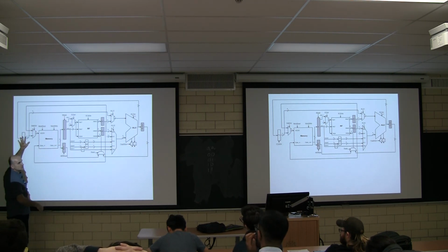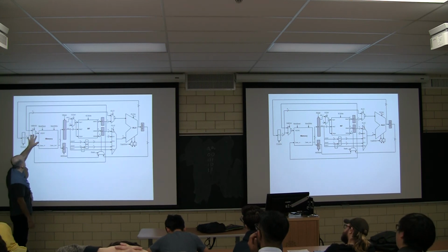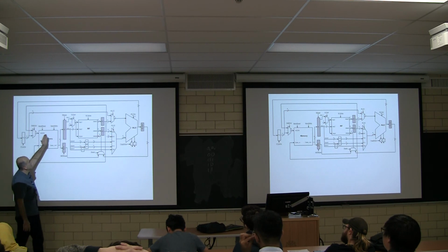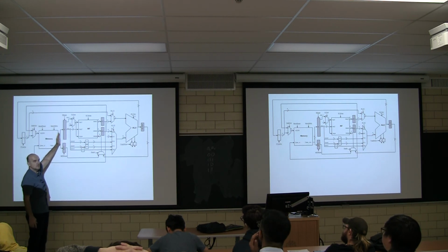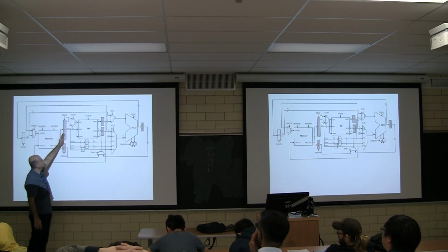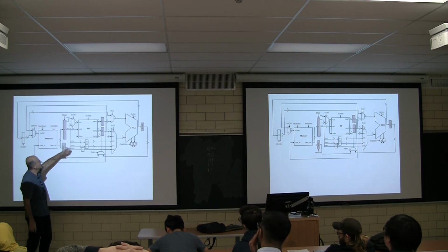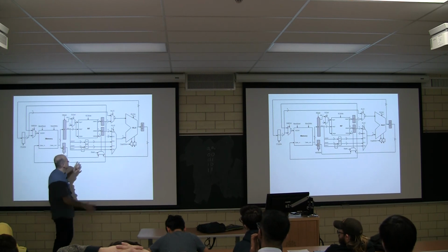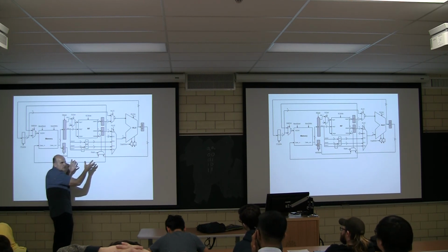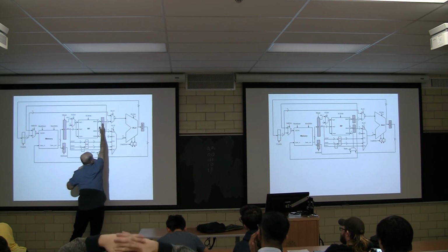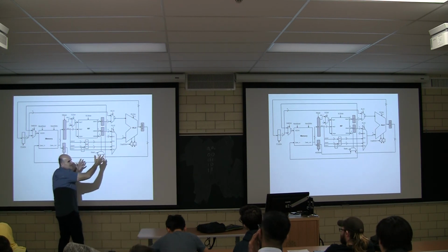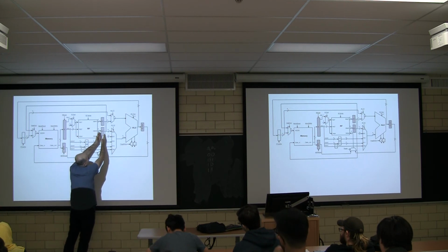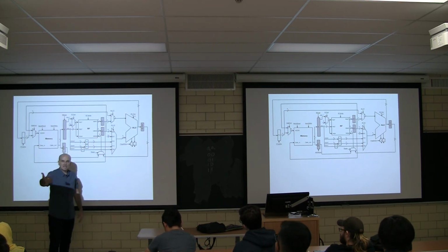So I have my program counter as before, and I can go to it directly from the program counter, or I can do PC plus whatever for the branches. We'll see that. Second step, at the end of the first cycle, we're going to produce the IR, the instruction register. After that, we have the register file. This will look almost identical to what we had before. There are 2 registers in between here because in the second clock cycle, we're going to be reading the registers from here, and we stage them in these registers so we can use them on the third cycle.